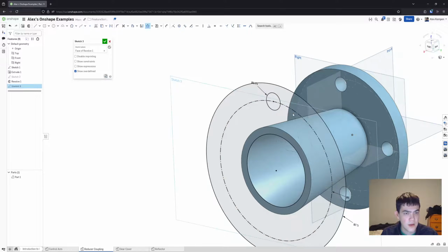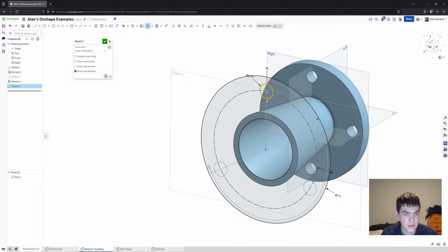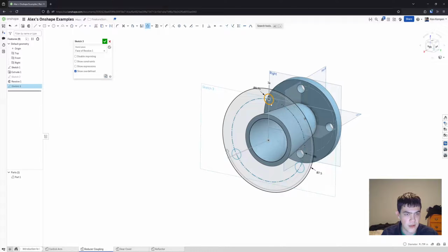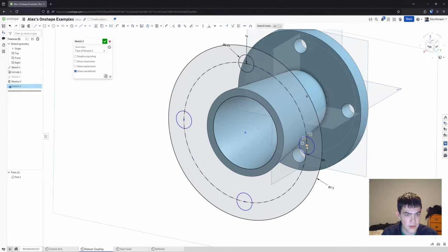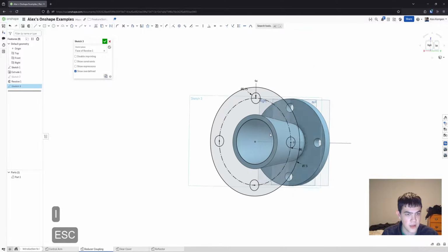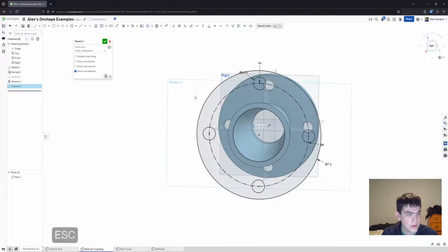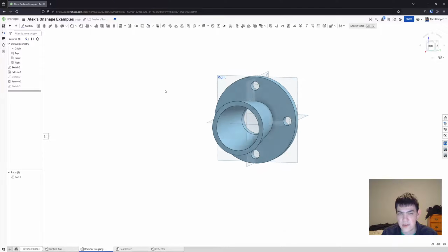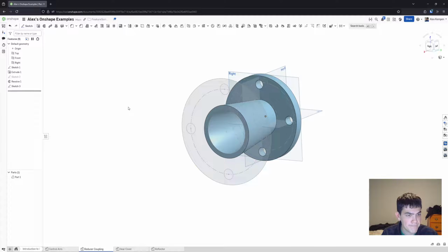Anyway, okay, and then I'm gonna go ahead and circular pattern this again, right? So once again, I click and then I get my preview. I can click to confirm. I'm gonna edit this before I confirm. And then I don't need this dimension, so I'll just go ahead and snap this to the full. I'll click to confirm that, right? It defaults to the origin, but I need to actually constrain it, so I'll drag it off and then make it coincident. And so now we're fully constrained. Cool. So I'll go ahead and confirm this sketch, right?